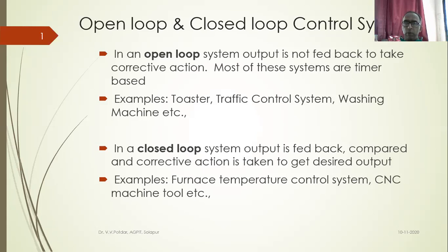Now, what do you mean by this open loop system? The output is not fed back to take corrective action. Now, take the case of a toaster. Domestic toaster, electrically heated domestic toaster. If you have used, you have seen, you put the fresh bread slice inside the toaster slot, set the timer maybe for 1 minute, 2 minutes, and then just put the toaster on. What happens? After 2 minutes are over, the toast pops up, and then you get the toast coming out of it. But why is it called an open loop system?